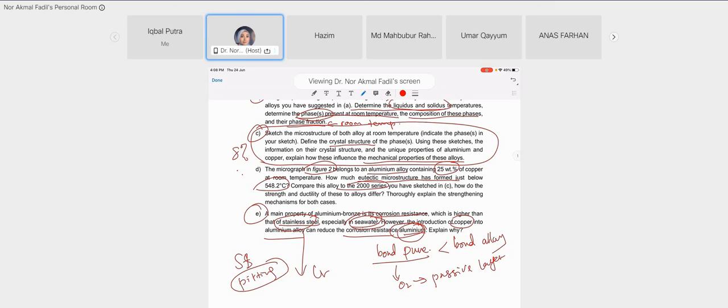Sometimes I have some kitchen utensils made of stainless steel. They look very nice, there's no corrosion at all. But when I pour water inside the item, some leakage happens. I cannot see the hole, because stainless steel is not resistant to pitting, especially in seawater. And if there's a hole, the chance of the iron reacting with the oxygen is high. Even though it has chromium, chromium is only active at the surface. In the hole, maybe it's not as active as the surface. So that one is stainless steel.